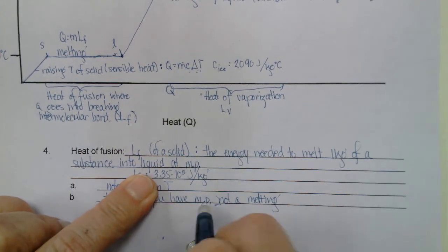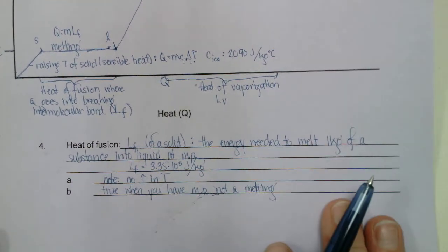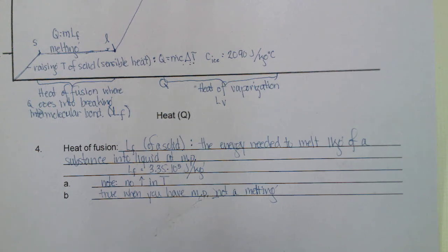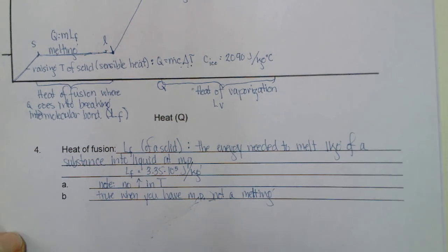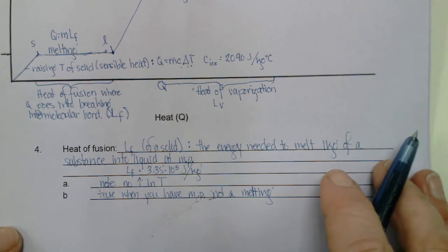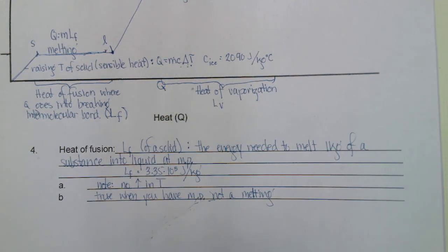So with an amorphous solid, all of the bonds are not equal in the solid. So some of them are closer, some of them are tighter, some of them are farther apart, some of them are looser. So because of that, it doesn't take the same amount of energy to break every bond. The easier bonds are going to break early on as it's adding heat, and the harder bonds are going to break later. But in the process, once I've started breaking some of these bonds, and I have a lot of them broken, I can start raising the temperature, but I still have other bonds to break.